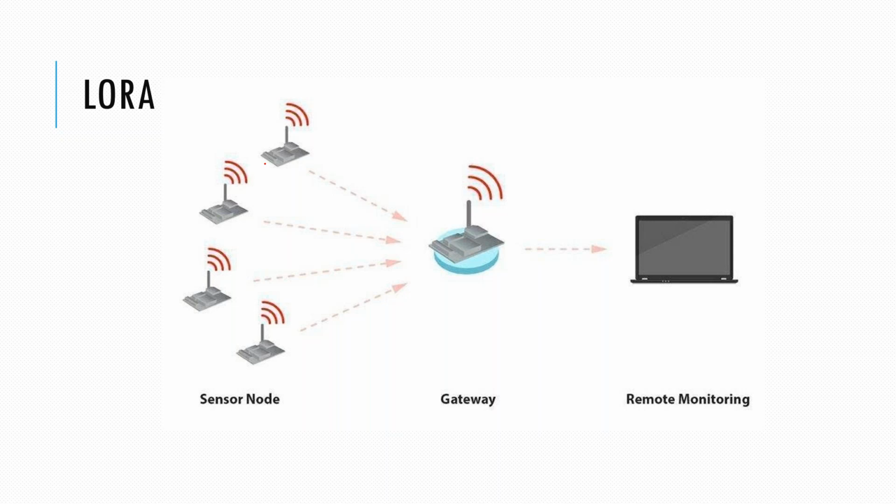So here we want a wireless networking technology which can work on very low power and cover a wide area. LoRaWAN is one of the solutions, and there's no bandwidth license we need to purchase, it is open bandwidth. That's why it is very famous in India nowadays. Its architecture is a gateway based system, and its range is up to 15 kilometers.